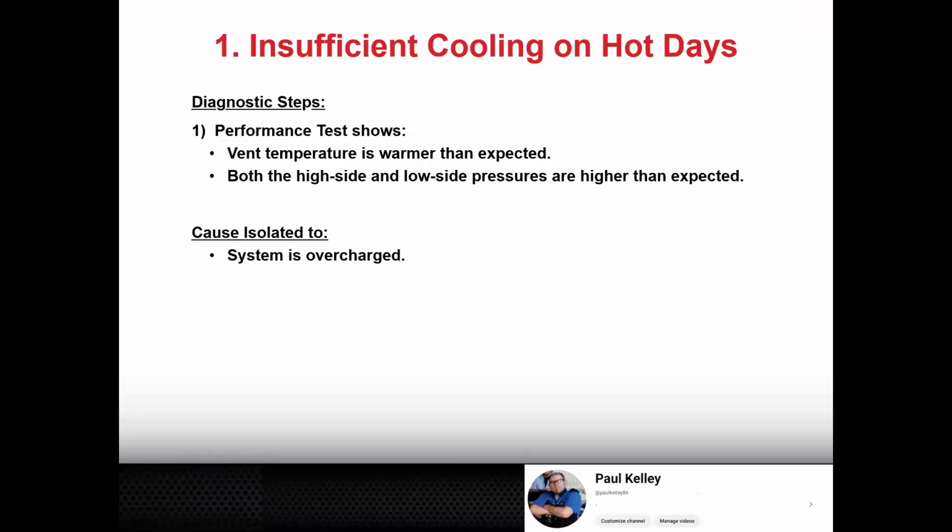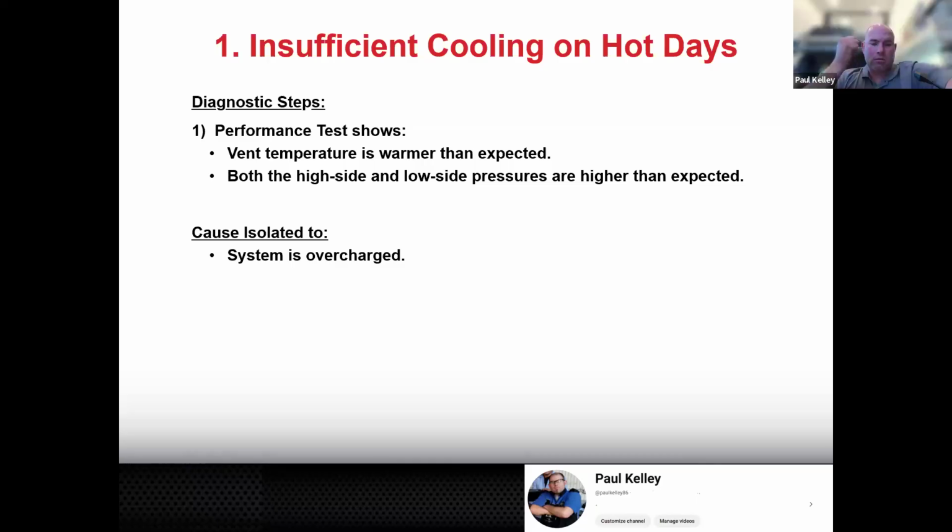Put up the gauges. Yeah, so my gauges are over there. How are you going to do it at the dealership? Well, it's okay if you use the machine just for the gauges. It's all right if you roll the machine over and you're like, well, I'm not going to recover it. I'm just going to check the pressures using the gauges. That's legit. That's fine. So you put the gauges on there and the high side and the low side are